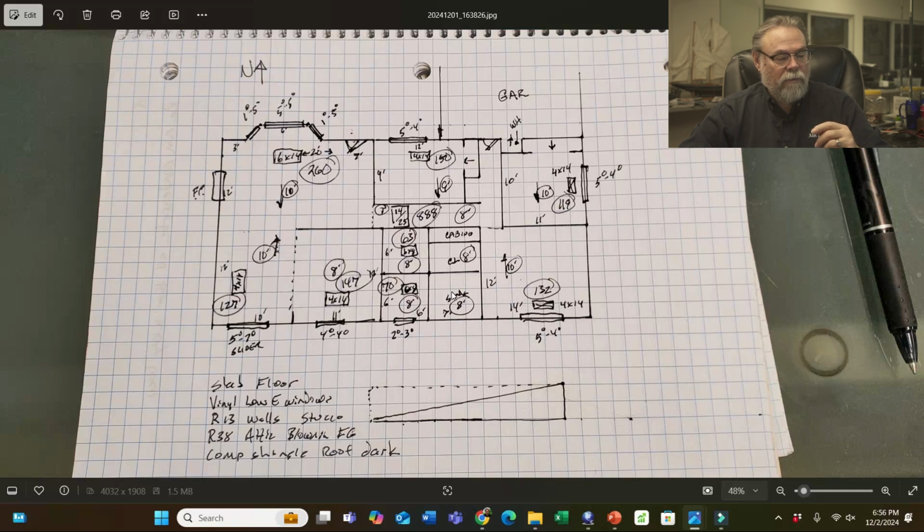So is this bathroom, this closet, this hallway, and so is this bathroom here. The rest of the rooms all have cathedral ceilings. Like I said, the trusses meet at the center. This house is 24 feet deep, and right down the center is where the trusses meet. Then they just frame down for all these 8 foot ceilings.